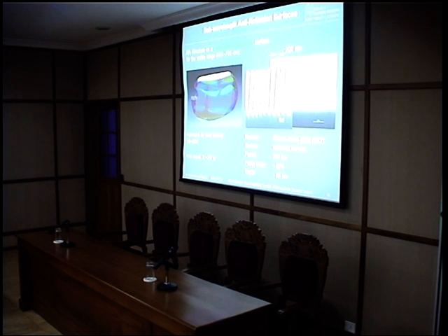And if you look at the surface of this barium crown glass, which is a BK7 glass, you see we structured it with a period of 270 nanometers. The filling factor in this case was 60%, and the depth was 65 nanometers. You can guess the scale bar here, this is 1 micrometer, so these are really very tiny structures. To look at it a little bit closer, here you see how it looks. The spacing between two ridges is 200 nanometers, or 270 nanometers to be correct.